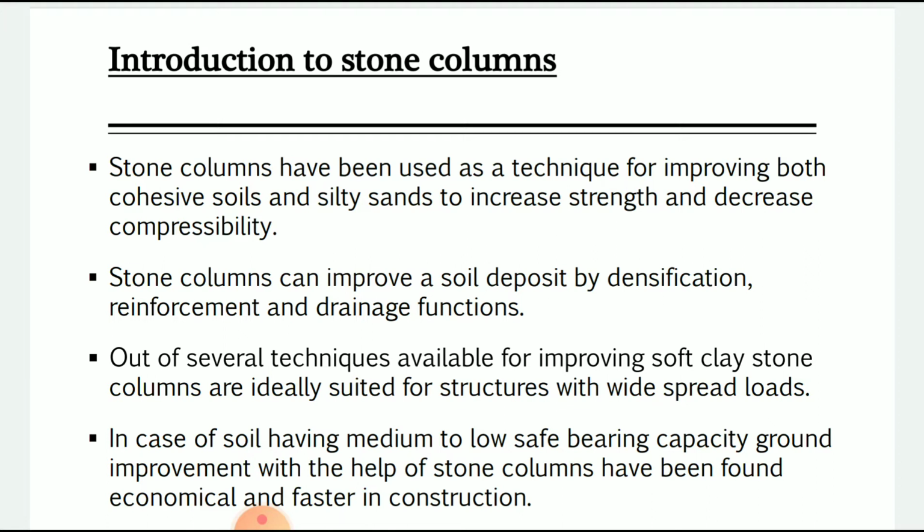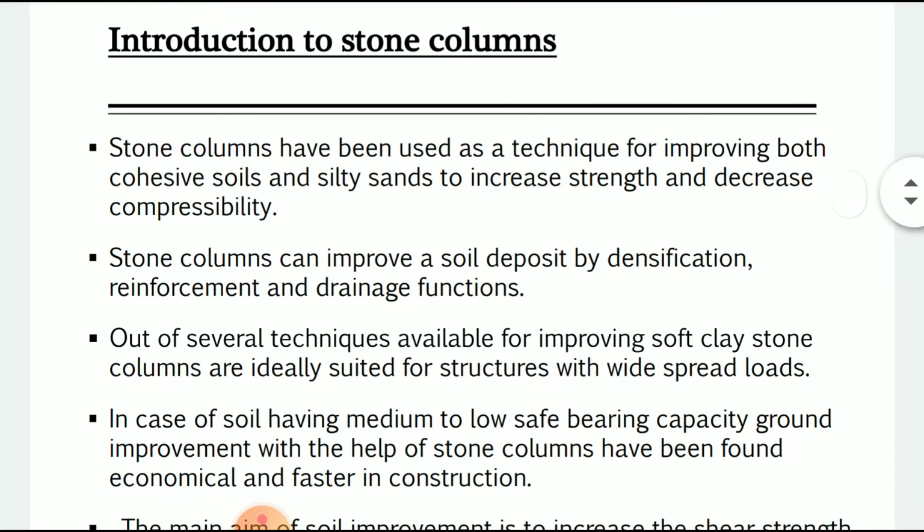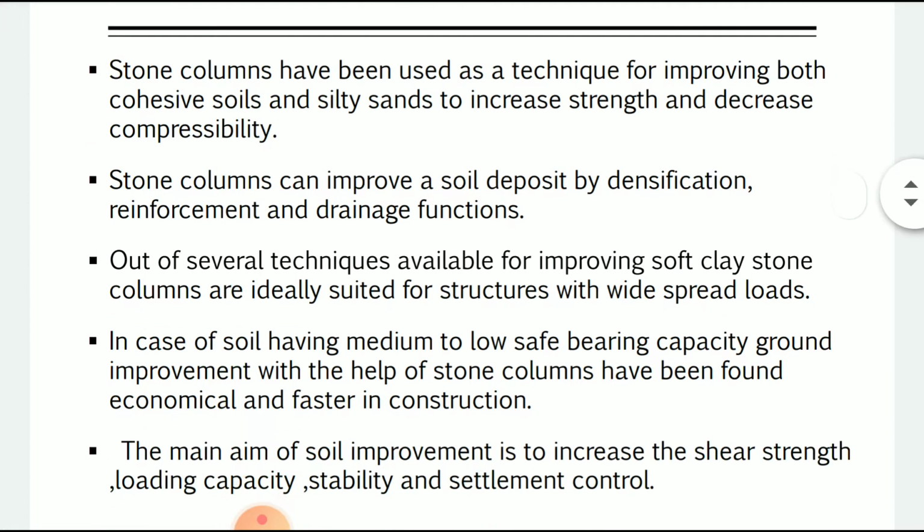Now, out of several techniques available for improving soft clay, stone columns are ideally suitable for structures with widespread loads. In case of soil having a medium to low bearing capacity, ground improvement with the help of stone columns has been found economical and faster in construction.